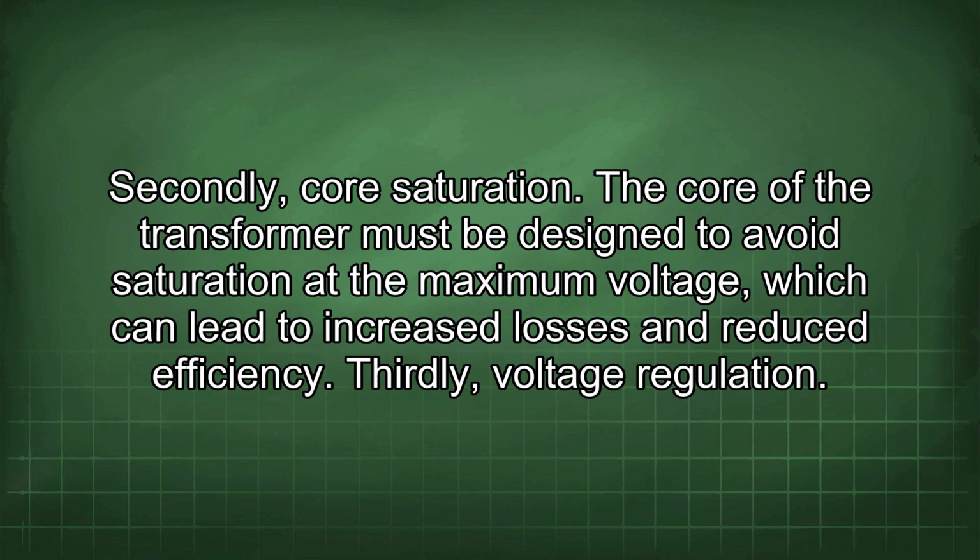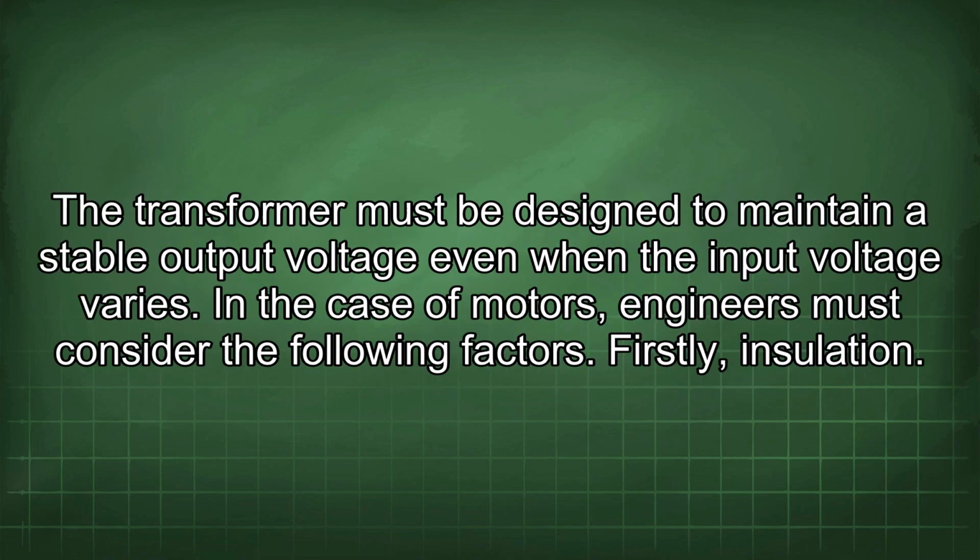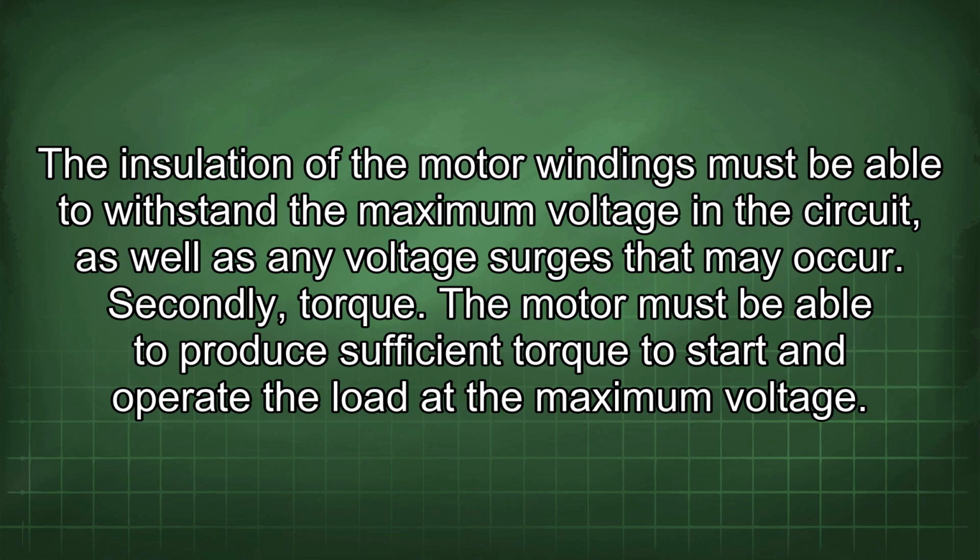Thirdly, voltage regulation. The transformer must be designed to maintain a stable output voltage even when the input voltage varies. In the case of motors, engineers must consider the following factors. Firstly, insulation. The insulation of the motor windings must be able to withstand the maximum voltage in the circuit, as well as any voltage surges that may occur.